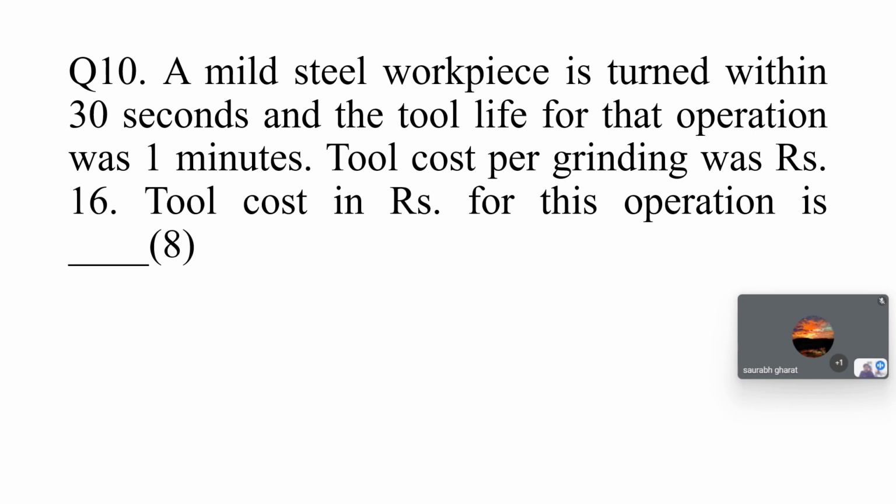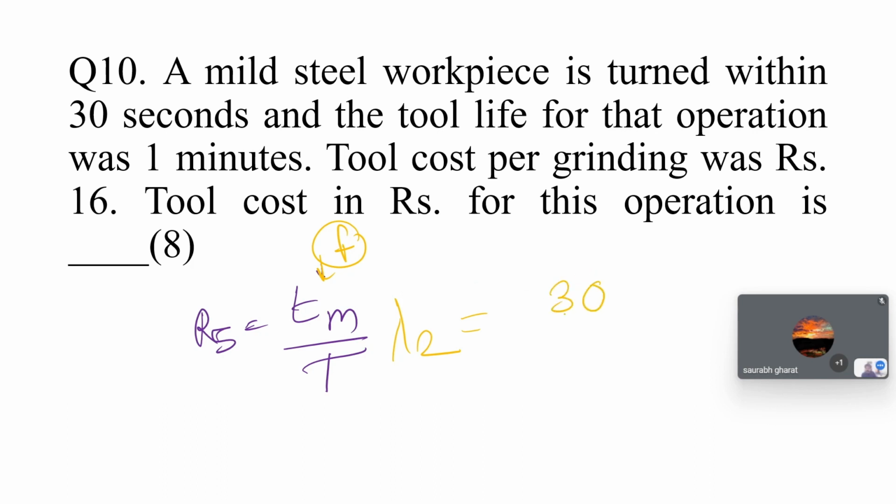So here we just need to calculate the frequency, and I know how to calculate that frequency. This will be our frequency, the time for which we have to change the tool, using the machining time and tool life. The frequency here we can change, since we are sending it for the next operator. We are not paying for that grinding operation, so every cost is involved here: machining cost, labor cost, overhead costs, the transportation cost. So what will be the answer here? TM, your machining time, is 30.